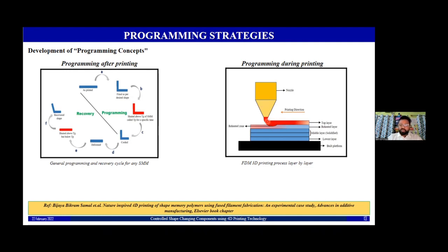material passes, and the hot polymeric material gets deposited on top of the build platform. So these two are done here. Once that is completed, the nozzle goes up depositing various layers of the material. It also gets cooled from below, so this cooling or quenching part is also done automatically during the process. That is the motivation for using fused filament fabrication for processing of shape memory polymer.